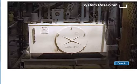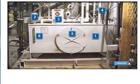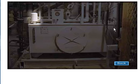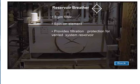System reservoir, 200-liter reservoir, provides oil storage for main system power unit. Reservoir breather, 5 micron, spin-on element, provides filtration protection for vented system reservoir.